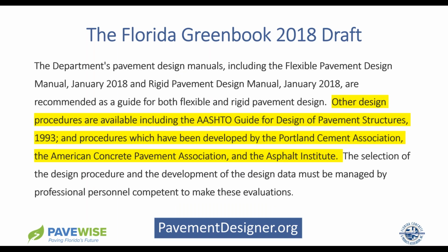The department's pavement design manuals, including the Flexible Pavement Design Manual, January 2018, and Rigid Pavement Design Manual, January 2018, are recommended as a guide for both flexible and rigid pavement design. Other design procedures are available, including the AASHTO Guide for Design for Pavement Structures, 1993, and procedures which have been developed by the Portland Cement Association and the American Concrete Pavement Association and the Asphalt Institute.